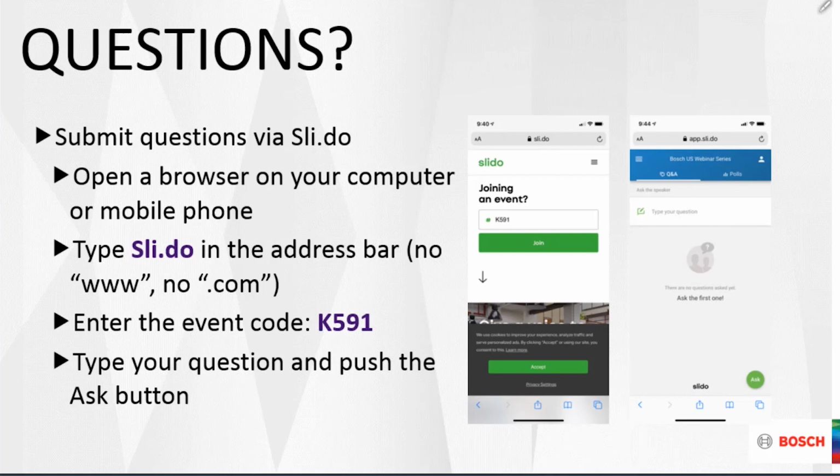Next question: when you are monitoring a door to see if it's been left open, do you need another contact for the burglar alarm? No, actually, when you're using that monitor delay and delay response feature, that door contact can be used for the burglar alarm and for this feature. When the system is armed, the contact will alert that somebody's broken in if they open the door. It'll activate an alarm, or if it's an entry-exit door, it'll start the entry delay. When the system is disarmed, it switches what it does, and now it's just monitoring the door to see if it's been left open too long. So no, you can use one contact to do both functions.